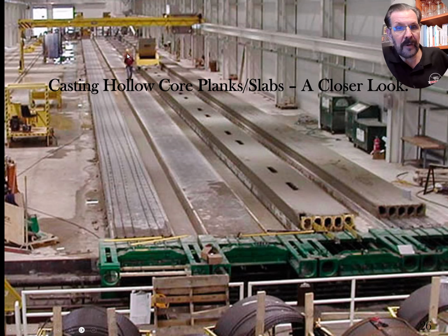So they've done that here. They're making one right here. There's nothing over here. They're shaping. They're on their way, buildings. And they've already stretched out the pre-stressing strands here, but they're not under tension. They're just laying here. But over here, they would be under full tension up above the floor. And you want them in the bottom quarter of the beam, is where they put them. But anyways, this is hollow core slab forming.